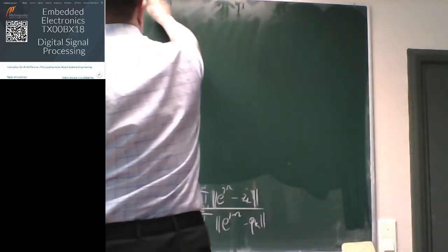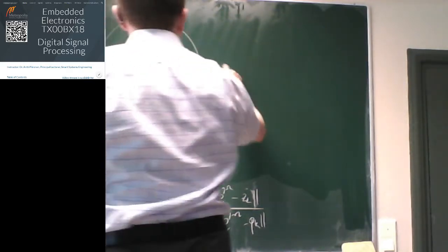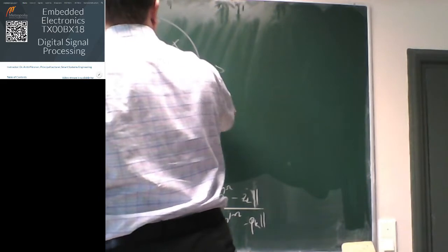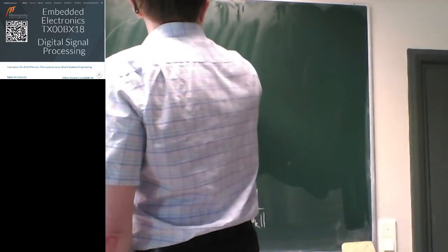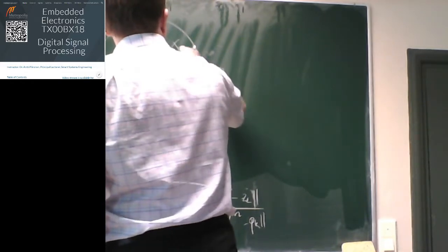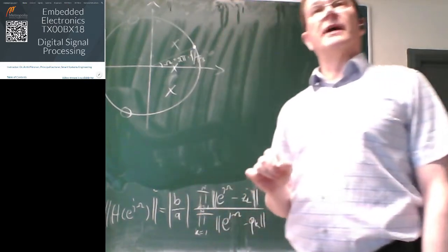Okay, on the zero-pole plot. If we have zeros, for example, at that kind of locations, and then a few poles here, and then we have this e to the j omega somewhere in here. That's the location on the unit circle, where this angle here is the omega, which is simply 2 pi times the current frequency divided by the sampling rate.